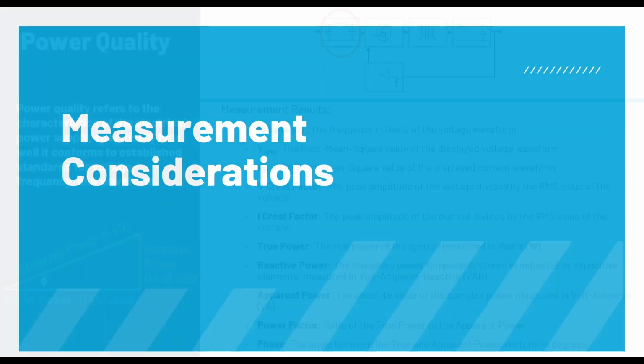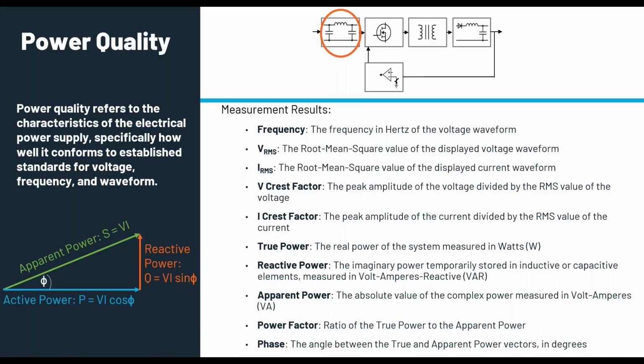Hello, everybody. So I would like to take some time to talk about some of the key measurements which Will was actually introducing on some of these sections of the switch mode power supply. So let's start from the different blocks. On the top, you see the input block here. So that's like an input rectifier block. So that's where I think we will do the power quality measurements. That's one of the important measurements here.